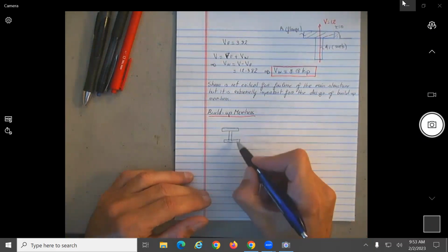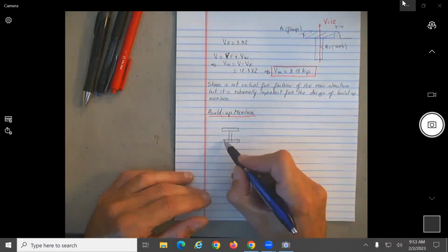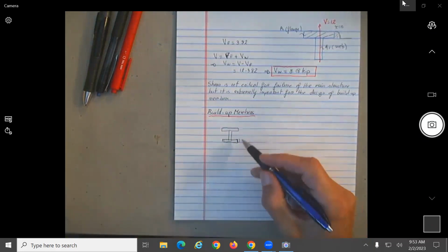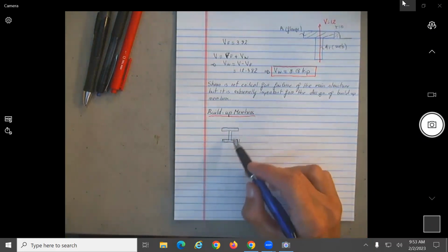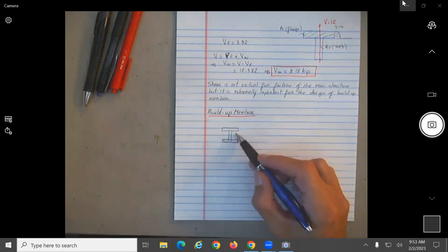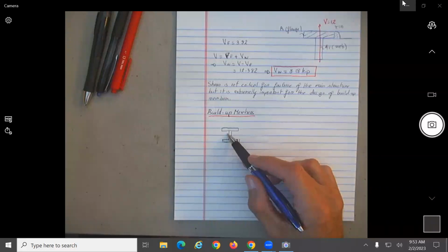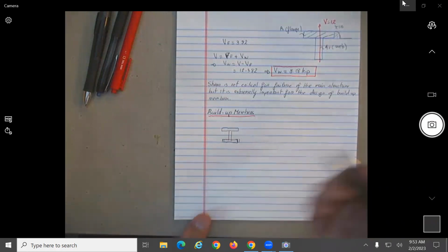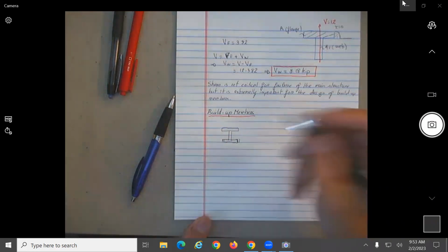I think we already discussed why all the area is at the top and the bottom. Why of this shape? That's where the bending stresses are, no? Top and bottom. Okay, do you remember? Here would be what? Shear, no? It's important here in the middle if they shear. But since those members generally would not break due to shear, that's why they use the least area there, no? Okay. So anyway, let's say you have this, and just like we were saying, you do the bed of